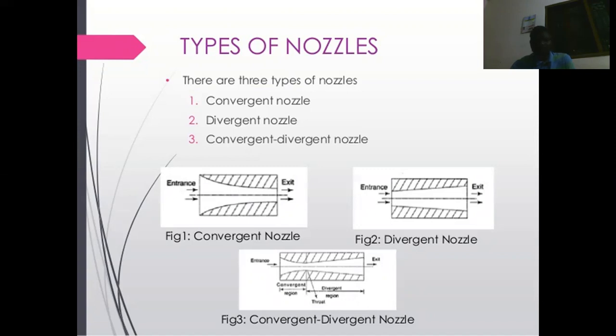In general, steam has very high pressure and very low velocity. The initial velocity of the steam when it is coming out of the boiler will be negligible, compared to the final velocity of the steam after coming out of the nozzle. The main use of the velocity of the steam is that velocity is nothing but kinetic energy.